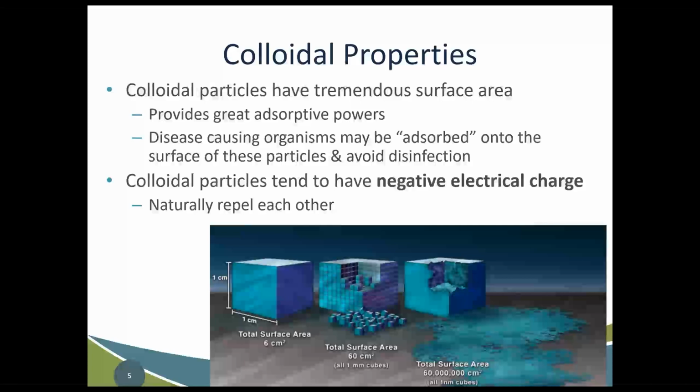We're going to touch on this throughout this presentation, but coagulation and disinfection, these are contact sports, so to speak. And so, you think about disinfection, you're looking at contact time. Well, if some of these microorganisms are adsorbed onto the surface of the particles, you may not get them in contact with your disinfectant, and they may be able to slip through the process.